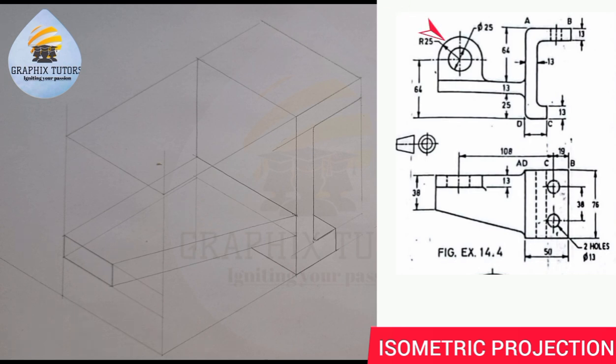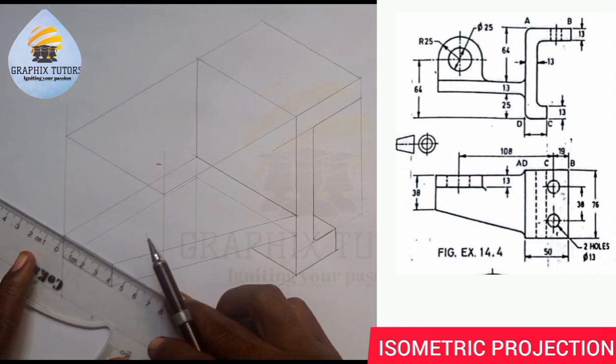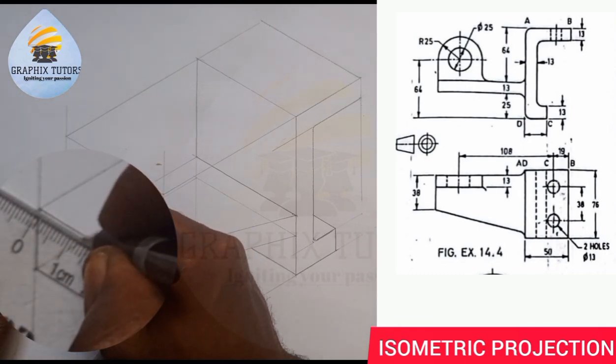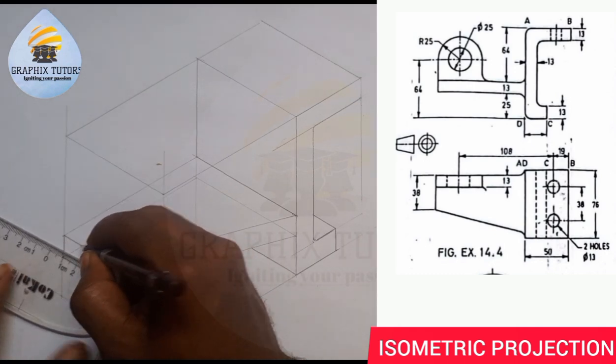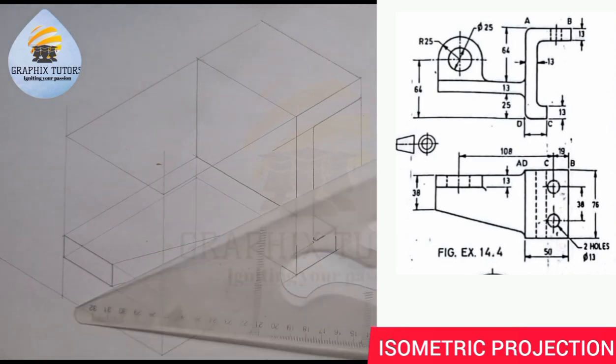Now the next thing we're doing here is that we have a circular figure here. Is that taken? Now to get to the center of that figure, this is what I'm going to do here. The thickness of the figure is 13 from here to here, 13, so I'm going to measure 13 at this point here. So from 0, this is 13 here. Then I'll take it backward this way.